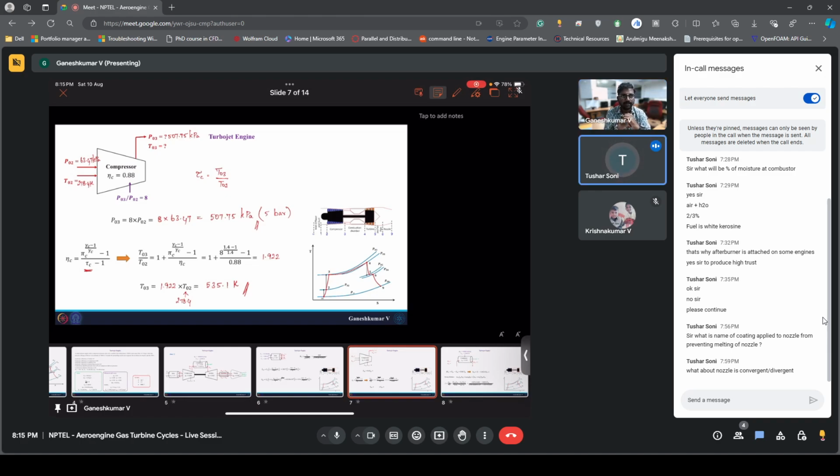The same process goes on there, but with a little bit different applications. In a turbojet you do not have any fan; you just have a compressor. In a turboprop you will have an additional fan, at the end, but it is not closed. But in a turbofan engine, you will have a separate fan, and also a controlled passage. The engine includes the fan plus the core part.